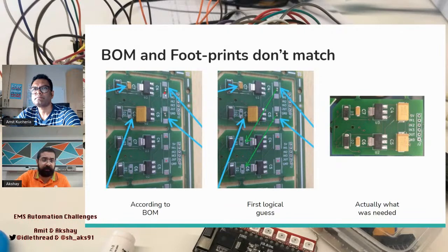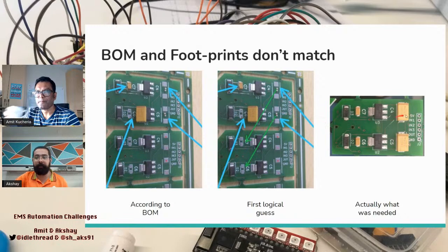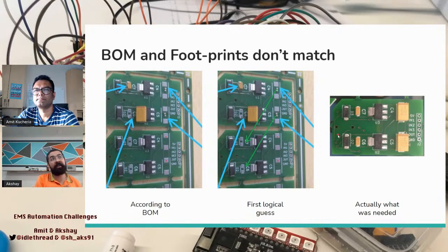These 2 are small enough, they can fit here. This one is big enough, he might be able to fit here. But then, in a conversation with the customer, we realize he wanted something else. He wanted the big tantalum capacitors here and the smaller ones here. So even thinking you had your BOM right and your PCB right, you still have opportunity to make things fail.